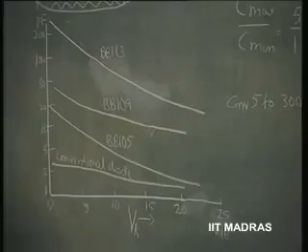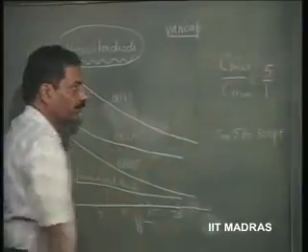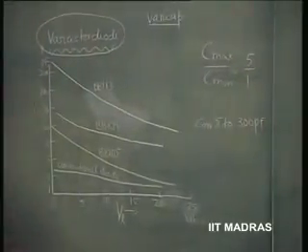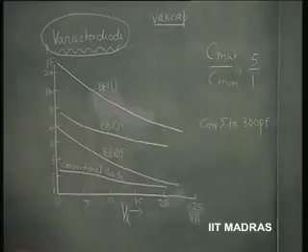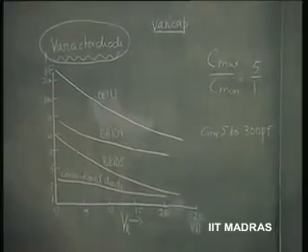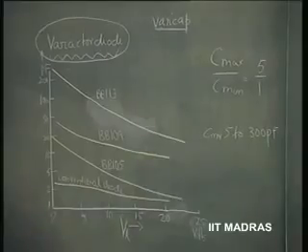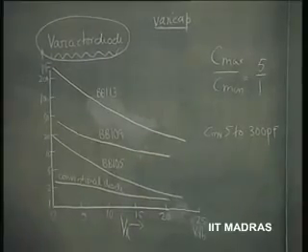So, maximum to minimum you should have normally as high a ratio as 5, typical. It is a good Varactor diode, and the maximum value of the capacitance itself depends upon the frequency range where you are likely to use it.